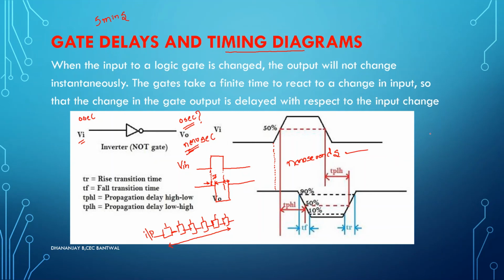That is why I said, try to reduce the number of gates in the circuit. The more the number of gates, the more the time delay. Suppose you have a lesser number of gates, lesser will be the time delay.